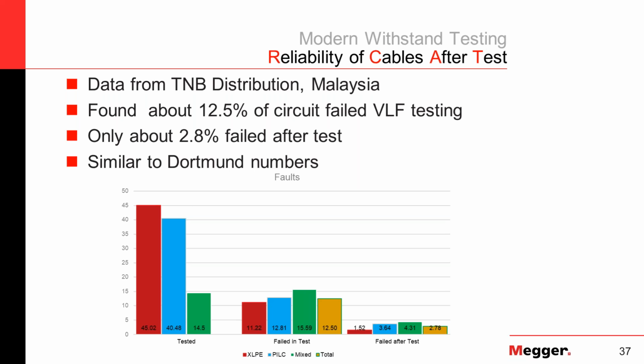And Mr. Mo pretty much stated that if we tested a circuit that we could not hold at 0.1 hertz, that circuit was at least 3 times as prone to fail after testing than the circuits that we tested at 0.1 hertz, which is another encouragement and a verification of the IEC rule of the strict requirement.